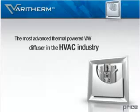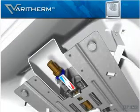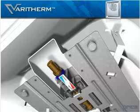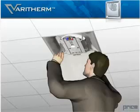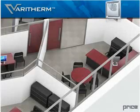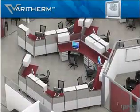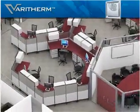Using thermal actuators, the Varitherm provides superior occupant comfort and control by effectively regulating the supply of conditioned air to the space without use of electric or pneumatic controls. The Price Varitherm is an excellent choice for local VAV applications such as offices, boardrooms, and small zones. The Varitherm can also be used throughout a building as a primary VAV system.